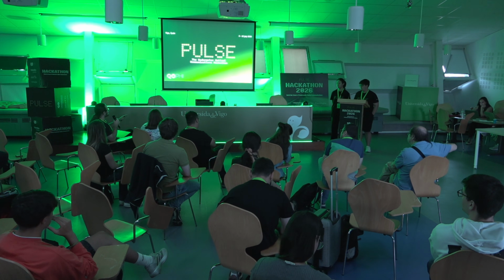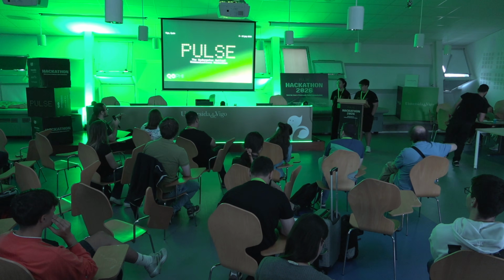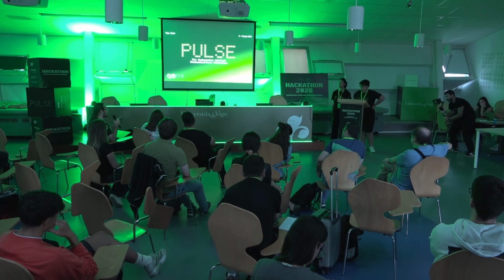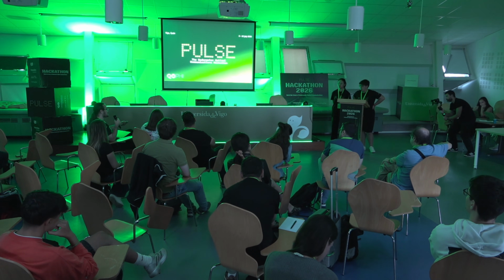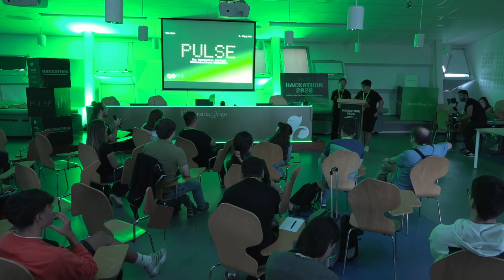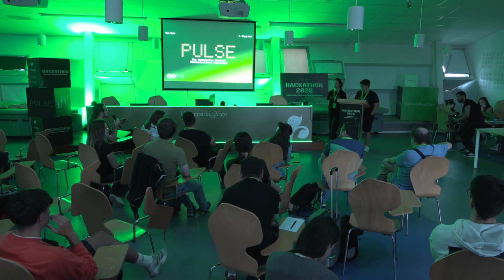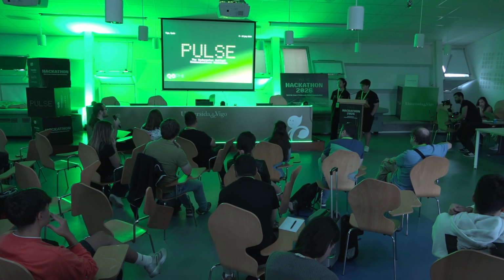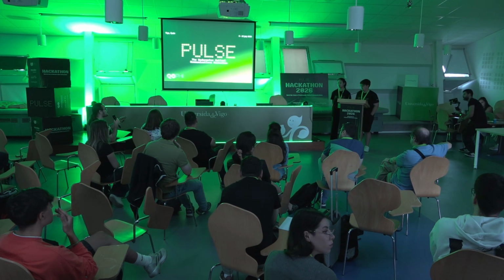You tell me. Did you make some simulation of the throughput in megabits per second? No. Okay. Because in this case, you also have to take the Manchester encoding into account, because it's not transparent. Do you know what implications it has on the throughput? The Manchester encoding has a really important implication on the bits per second that you can exchange.